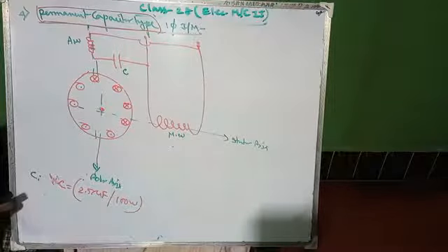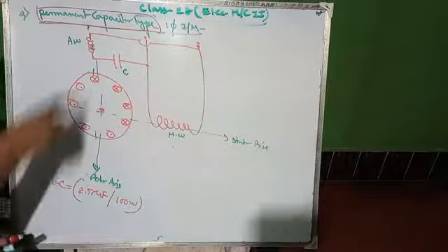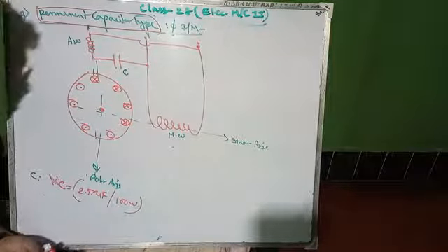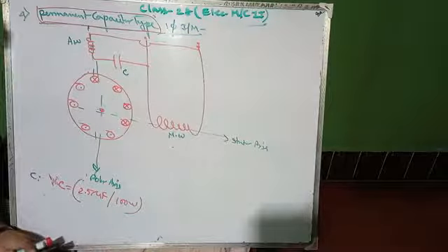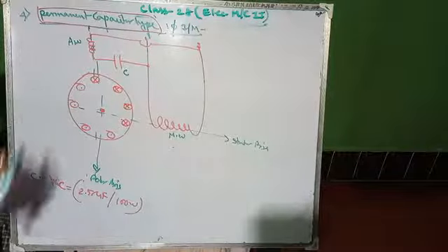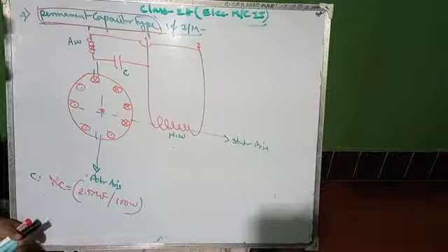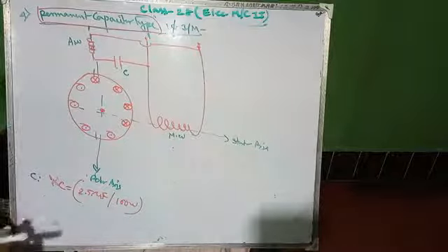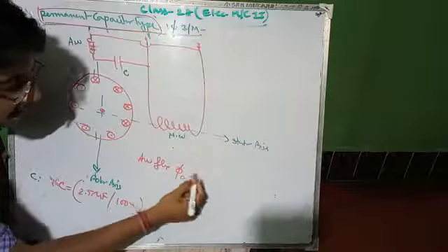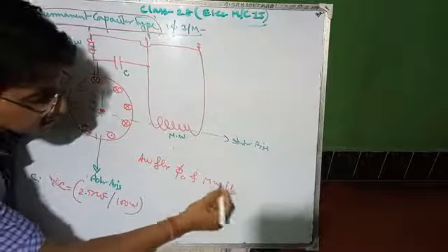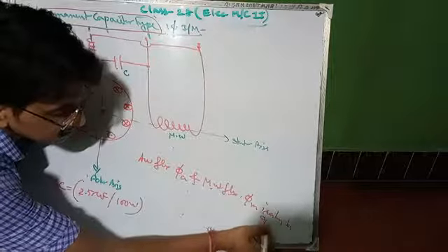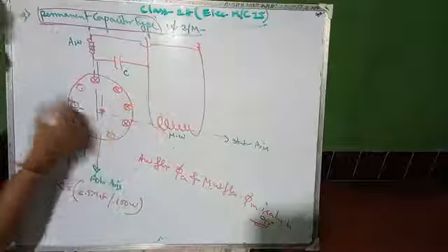Since the auxiliary winding is always present, this type of motor is called a permanently two-phase motor, and it always remains balanced, because the phase angle difference between the auxiliary winding flux, phi A, and the main winding flux, phi M, is always 90°.